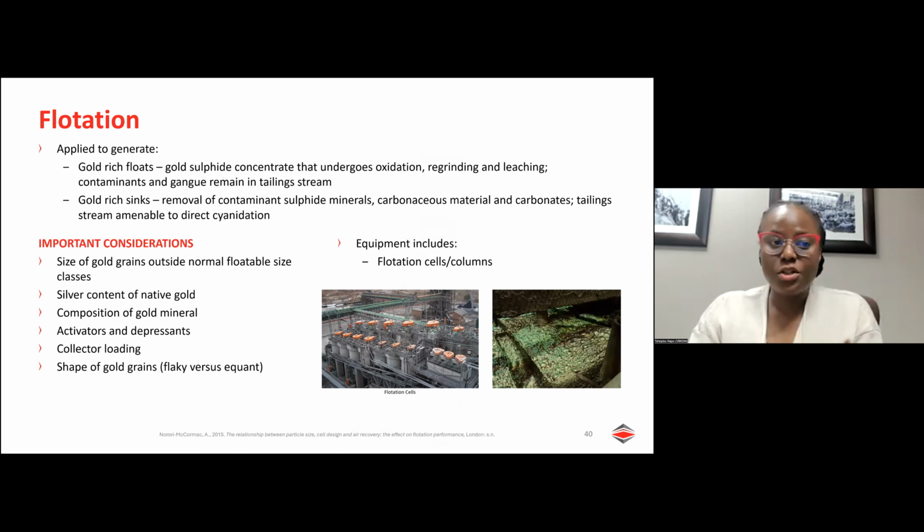Okay, then flotation is a concentration stage that removes undesired material from your stream. For example, if you have a stream where your main minerals are gold oxides, then flotation will remove your sulfides and your carbonaceous contaminants in the floats. It is then up to you when you are doing the design of the plant, whether you're going to treat those floats or discard them.